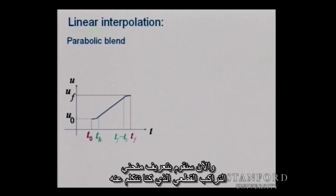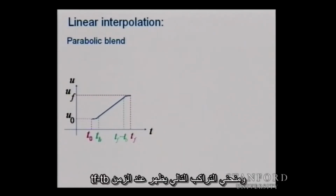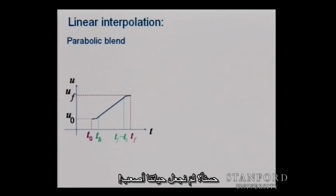Now we're going to introduce these parabolic blends that we were talking about. So we have the t sub 0 is the starting time, the t sub f is the ending time, and then we have this blend, and the first blend occurs at time t sub b, and the next blend is at time t sub f minus t sub b. So we'll be assuming that the length of each of the blends are the same for simplicity. Why make our life more difficult?